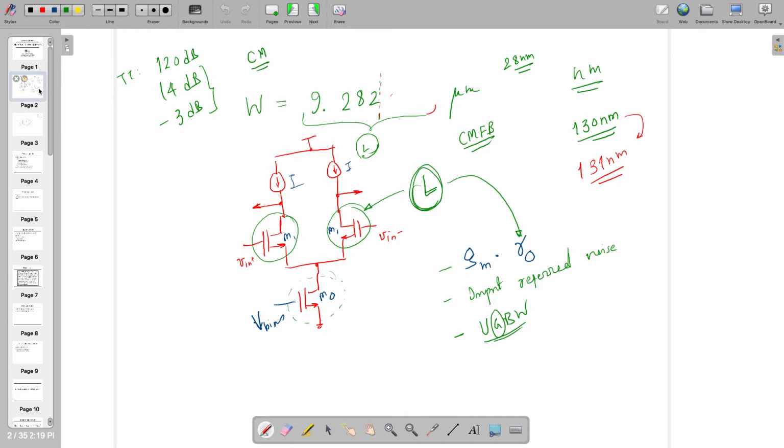Look, if I'm doing this for a circuit which looks like this one, it's sensitive to process for sure. Common mode voltage is sensitive to process because it is not the one which you expect. So what do you think the output will be here? I should say common mode voltage, not gain. Here, let's assume that the supply is 1.8.